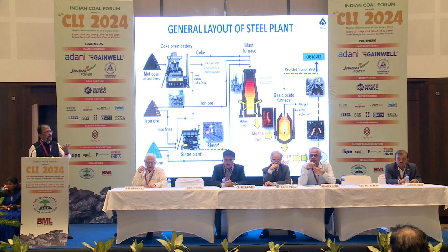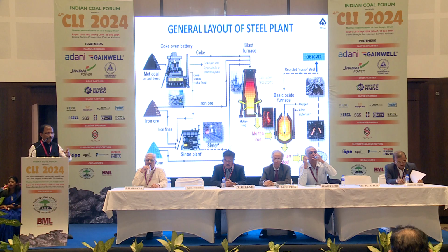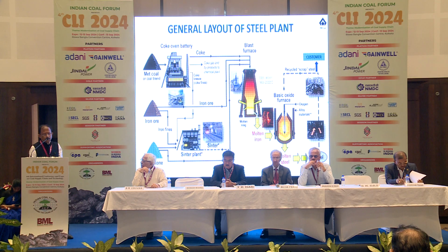Because we do not have any pellet making facility, we are sending our iron ore fines to pellet manufacturers, and in turn we are getting converted pellets from them. All these things go into the blast furnace, and we get hot metal. Hot metal is not a pure one. It has impurities: the carbon percentage from the coke is high, and you have silicon, sulfur, phosphorus, all the impurities.